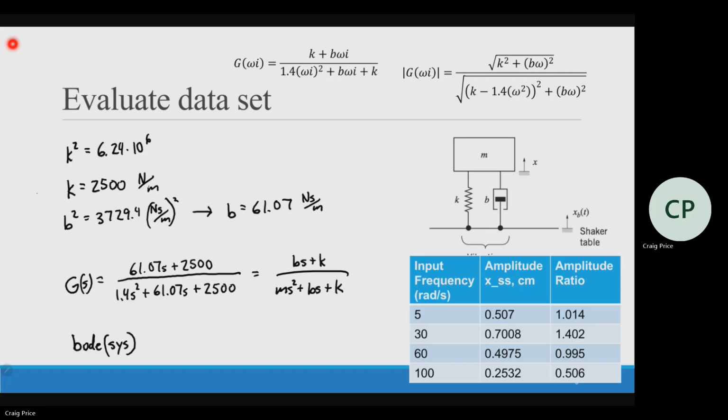By the way, what is the DC gain of this transfer function? It is 1. If all the s's go to 0, I'm left with this over that. That's 1. So the DC gain, which means that at our low frequencies, the output basically matches the input. That's what we see here. So K should be equal to 1, which means our starting point, 20 log of 1 equals 0. Our Bode plot should start at 0 decibels.